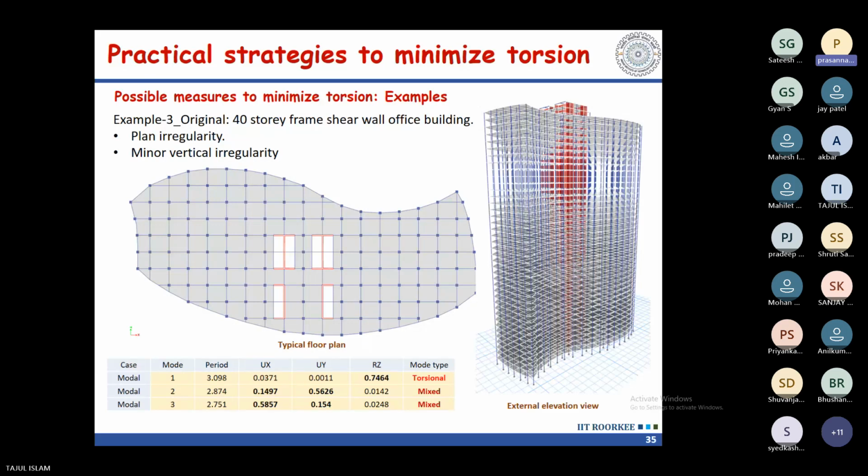Normally in an office building, these are at central locations. They never allow that; they will allow only the periphery of the building for staircases and core walls. Normally these are regular structures. If I go and design it, the core walls and staircase will happen on one side of the building. Only one side you have the core wall, and the other side you will not have anything, only a beam frame. A flat slab system and beam frame will be there like that. That is what you need to change. That kind of configuration will come into the picture.